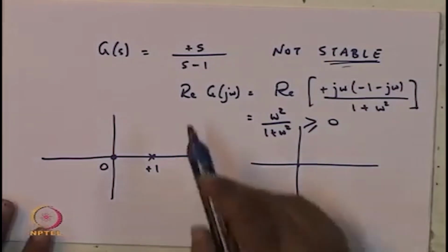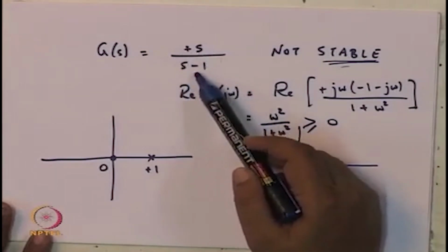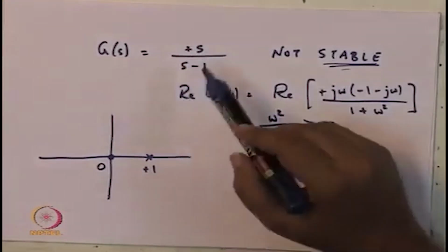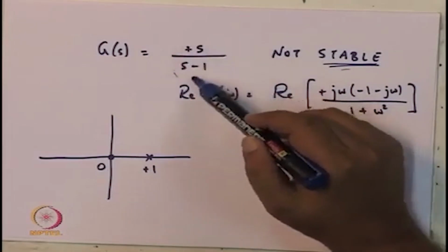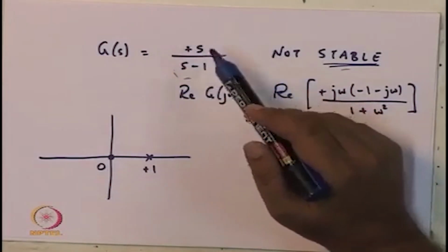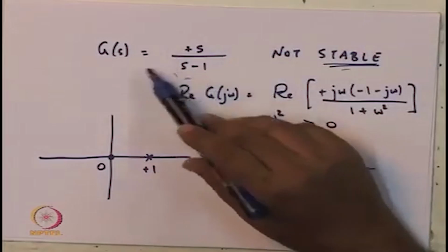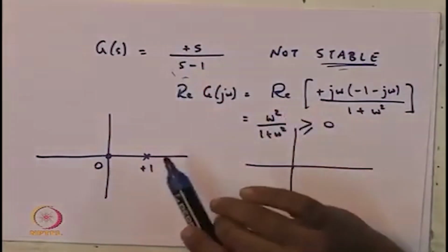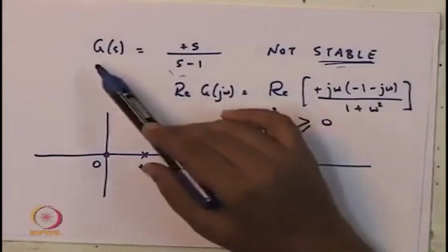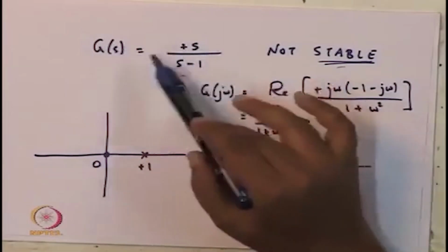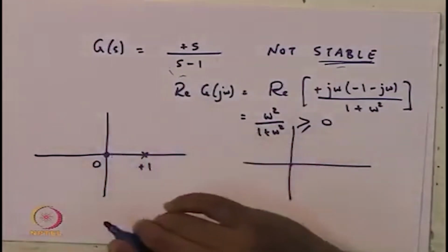So, it turns out that if you have a transfer function like this, it would not be possible to synthesize a circuit which has this transfer function using purely passive elements. And the reason for that is because this G(s) is not stable. As a result, the associated storage function that you can get for this particular transfer function is not going to be positive definite. Okay.